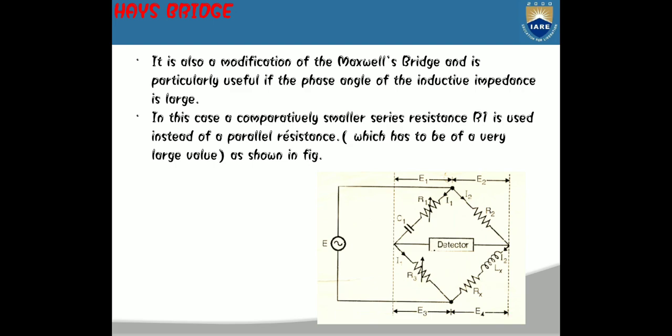For ideal inductors, the relationship is linear, so that the inductance value at an arbitrary frequency can be calculated from the inductance value measured at some different frequency. Unfortunately, for real components, this relationship is not linear, and using a derived or calculated value in place of a measured one can lead to serious inaccuracies.